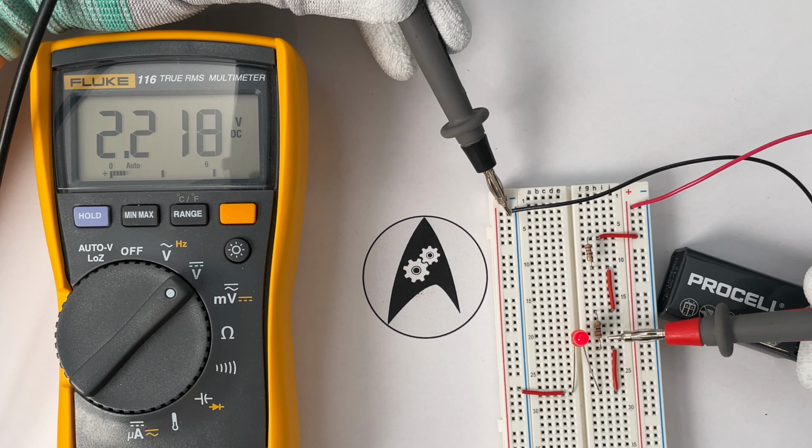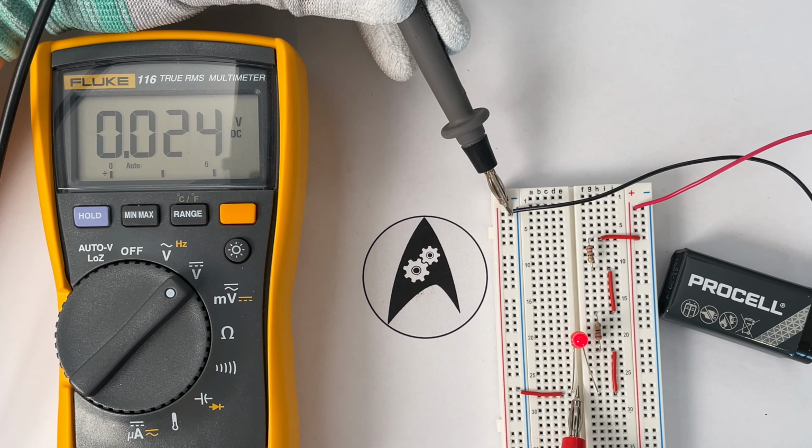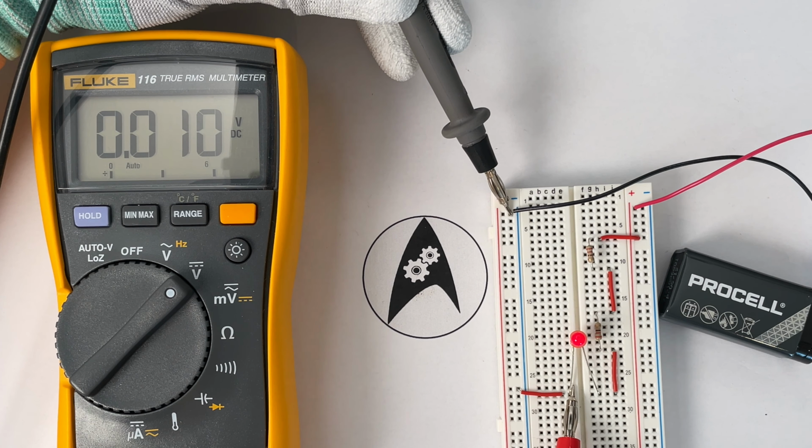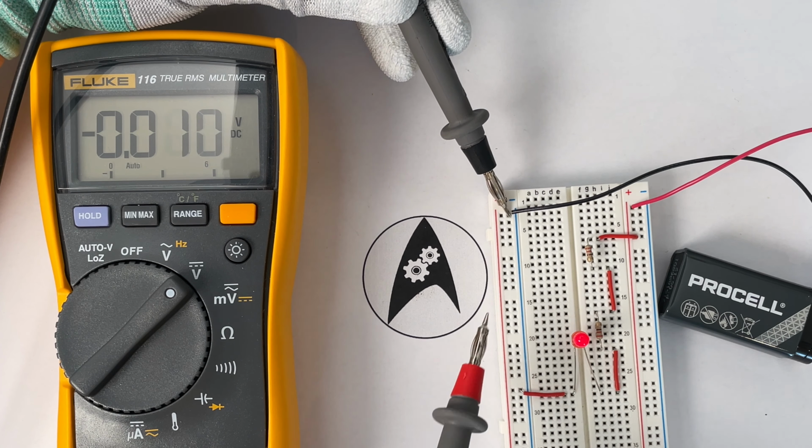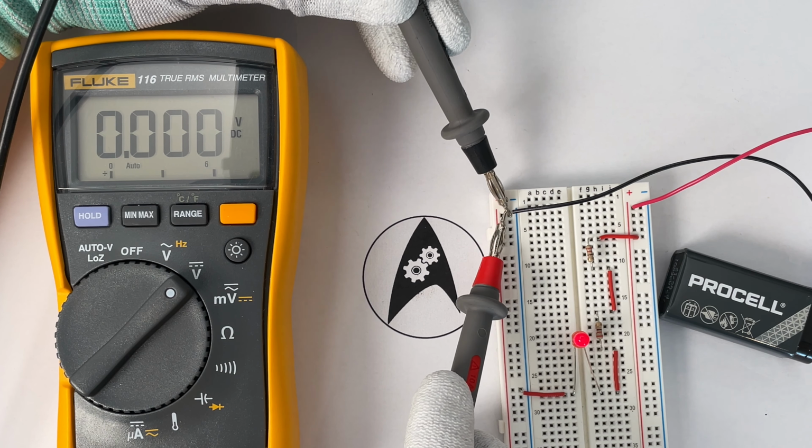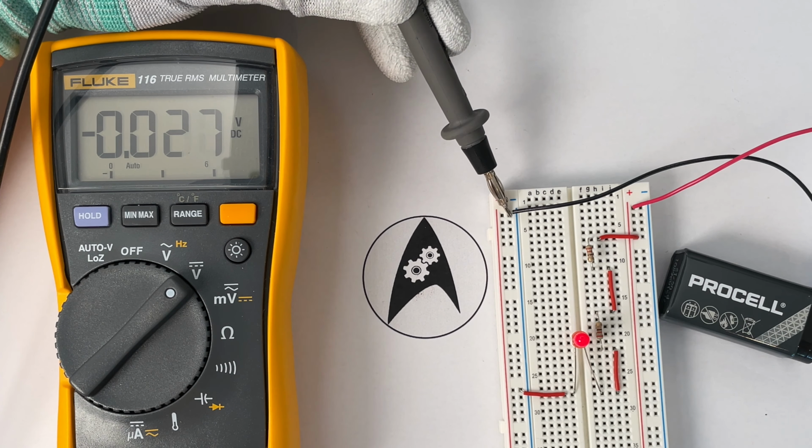As soon as they have crossed the LED, which I can verify by putting the positive tip to the left leg of the LED, the potential is almost down to zero. It's only at 0.01, roughly, even less volts. And as soon, obviously, as I connect it to the negative terminal, it's really down to zero. Now there's absolutely no potential which I am measuring. So potential, this is what you need to remember, is always relative to the negative terminal of, for example, the battery or the power source you are using for your circuit.